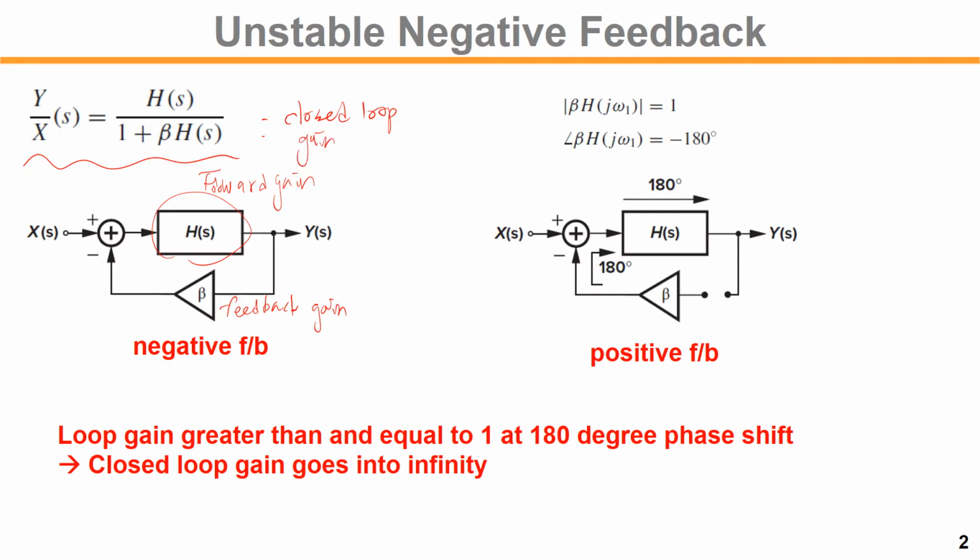Gain. So if you do some perturbation analysis, let's say if the input goes up, the output of the subtractor goes up, the output of H goes up, then feedback goes up, and then it goes down, right? Coming back, it will go down. So inside the circuit, it tries to make things not change, right? So we want to recover from small external variation, track the input variation, and make it less effective. So this is negative feedback.